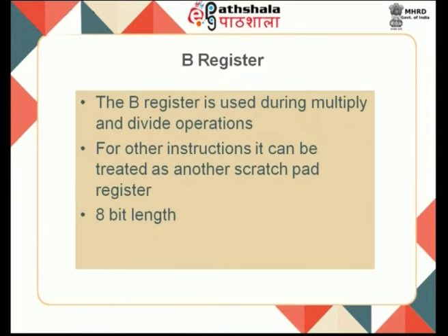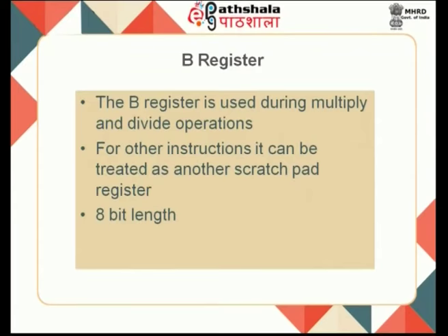The B register is also a very important register for processing. Usually in arithmetic, for multiplication and division operations, one of the data is stored in the B register, and otherwise it can be treated as another scratch pad. This is actually similar to the A register. It is also used as a scratch pad register. It is also 8-bit length, as the 8051 is an 8-bit processor, and all its registers are 8-bit length.